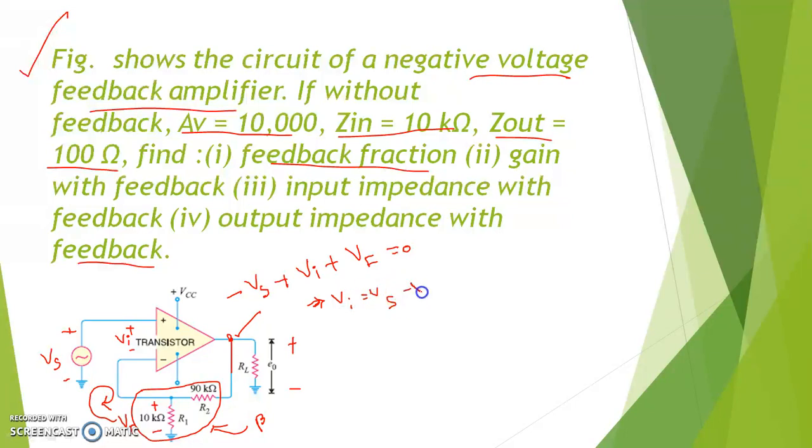So to get the expression of the original input of the basic amplifier block, we have to apply what? KVL in the input loop. So no doubt this is series mixing. So this is voltage sampling series mixing feedback topology, or voltage series feedback topology. Clear? So this is voltage series. Now see, we will draw the basic feedback topology from this name. So voltage series.